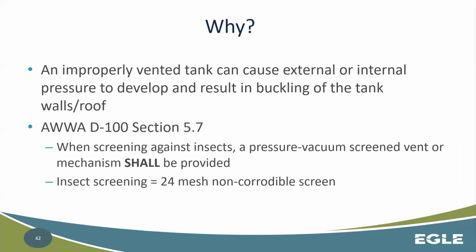So essentially, why do we need to have airflow? Well, obviously, you can have large pressure swings as your tank fills up or goes down. You can have buckling. You can have high pressure issues, with things blowing off or something like that. You can have collapsing, like this picture I will show in a moment.